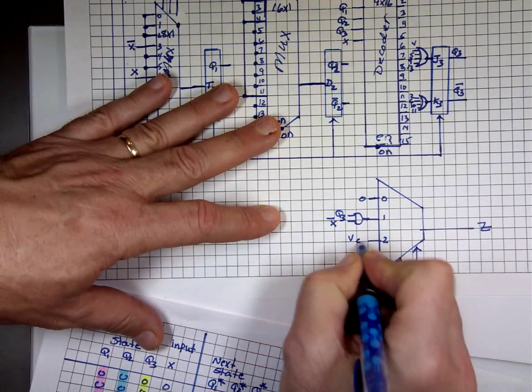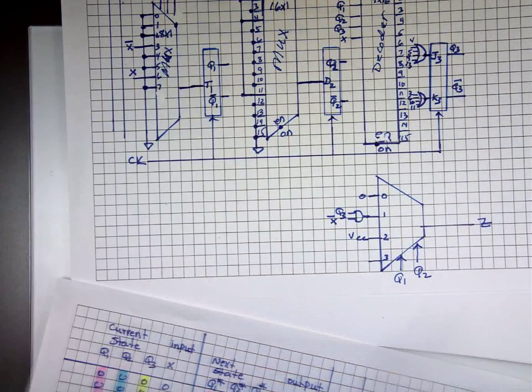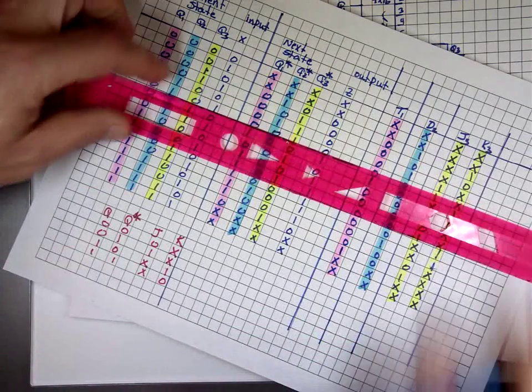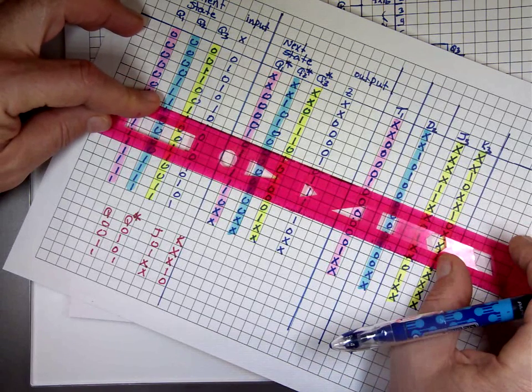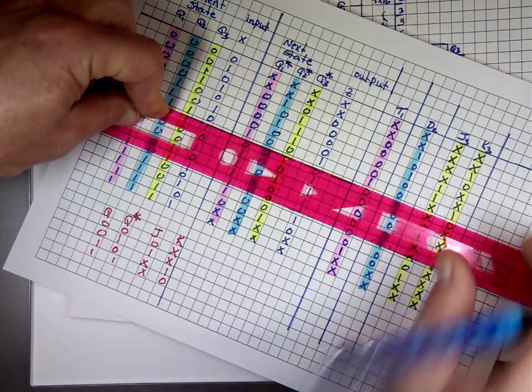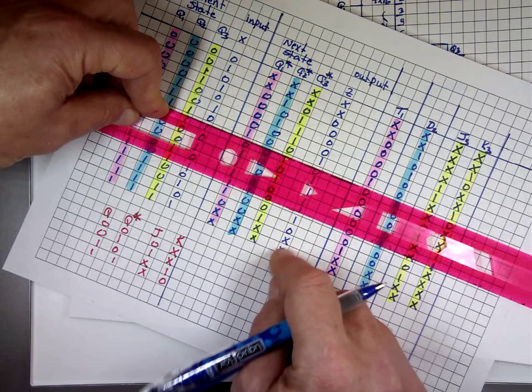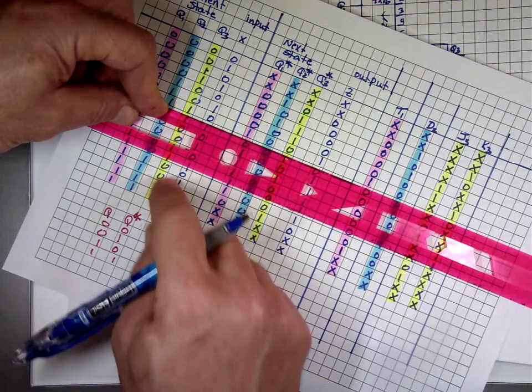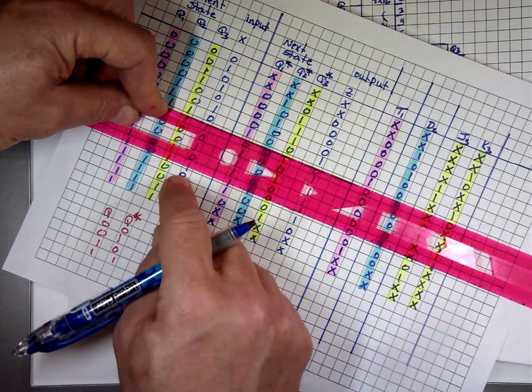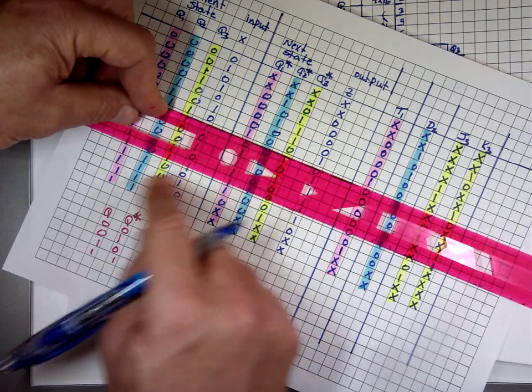And the last one is the last 4. 1 and 1. Well, if you don't care about these, you can make them zeros, right? If you make them 0, you only want to get a 1 when Q3 is 0 and X is 0. Put an AND gate with Q3 not and X not.